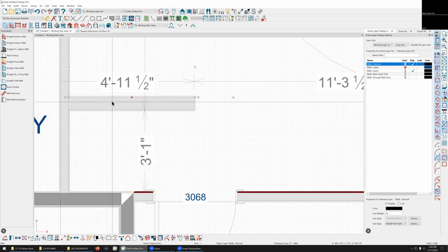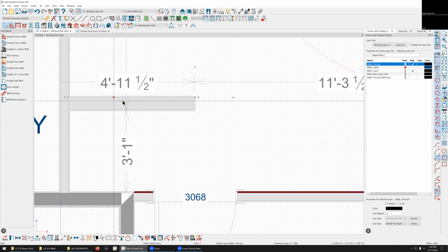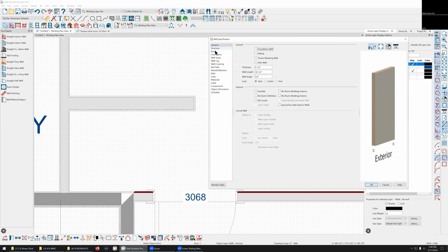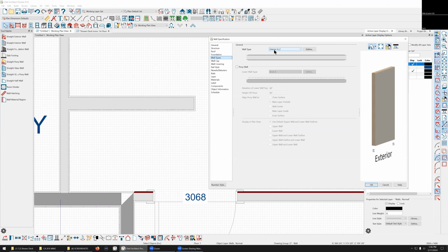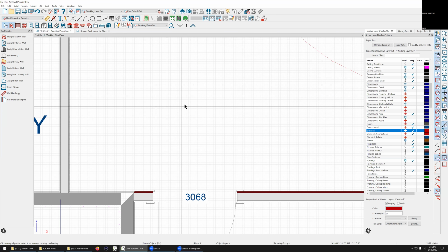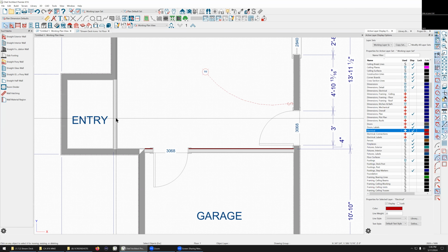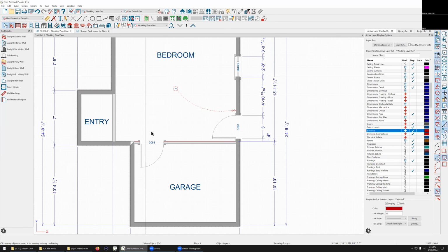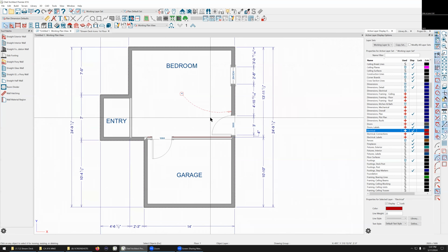And what's bad about that is it's no longer an interior 6. It's now a custom interior 6. You've created a new subset. I know it. If you do that plus deal, you're creating a new wall. And so I like to just minimize that if I can. I know it's more steps, but these are some of the things that, I know some people are going to say, "Oh, that's so picky. Why can't you just do this or that or do the workaround?" Every little thing we're talking about shaves time off your project.